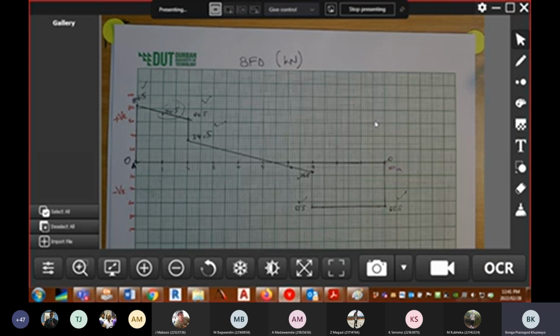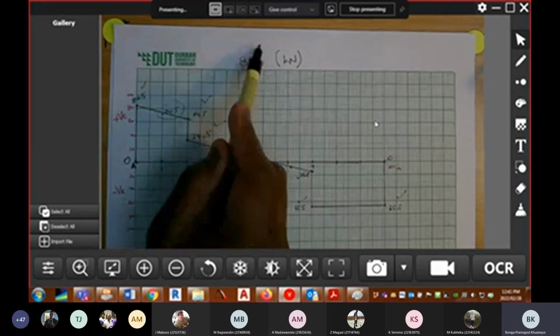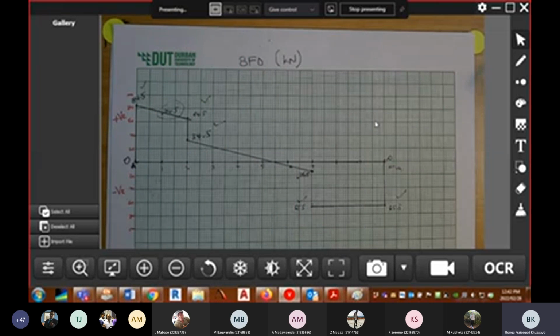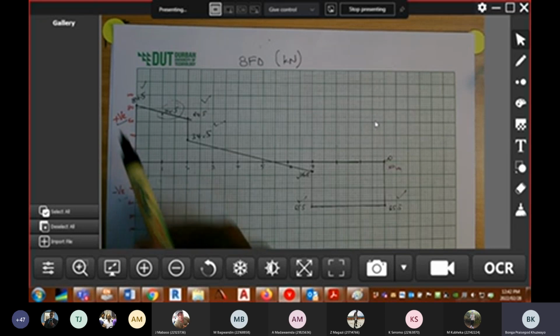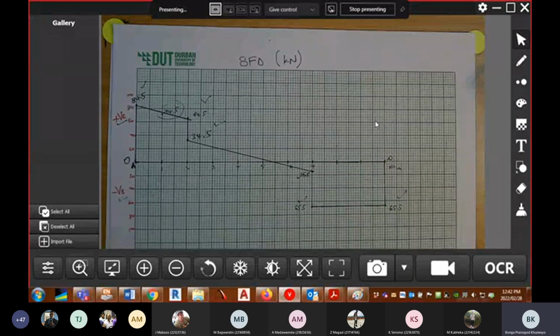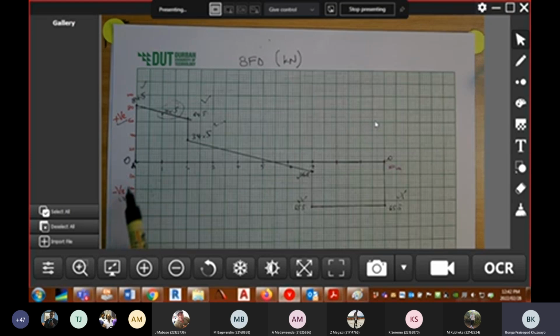So you need to tell us that this is the shear force diagram and the units you're using, kilonewton, and then you need to show us which side is negative shear, and which side is positive shear. And as far as these diagrams are concerned, if it's half mark, then it's a tick with that line there. It's like a half tick. So that's how we show it, right? Then it's obviously a mark or two for getting the whole shape correctly, the entire shape. Sometimes we do it like that. So if the entire shape is correct, then you get the 2 marks.